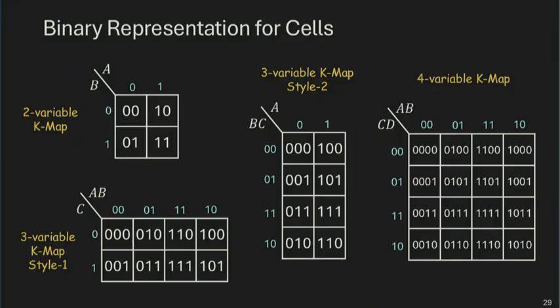You can have a 4x4 Karnaugh map. And for all of these rows and columns, when you have 4 elements, they'll follow the 00, 01, 11, 10 order. And this is actually called gray code. When we saw BCD, 8421 BCD, XS3 BCD, there was a table having multiple codes, and one of them is a gray code. And that satisfies this kind of adjacency relationship. Neighbor, neighbor, neighbor, wraparound neighbor. By following this gray code or Hamming adjacency ordering, you get to put all the neighbors next to each other.